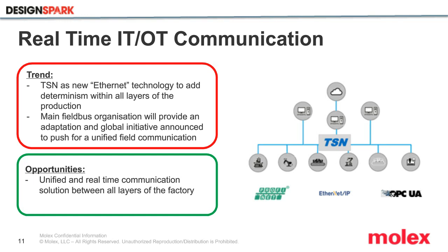Today, TSN is finding some consensus in many industries, for example, in audio-video broadcasting, for in-vehicle communication, as well as in industrial automation. So TSN is seen now as a replacement of the current Ethernet transport layers, and brand new initiatives from large automation players are pushing TSN together with OPC UA as the long-term replacement for the traditional fieldbuses. Profinet and Ethernet/IP may be replaced by OPC UA.